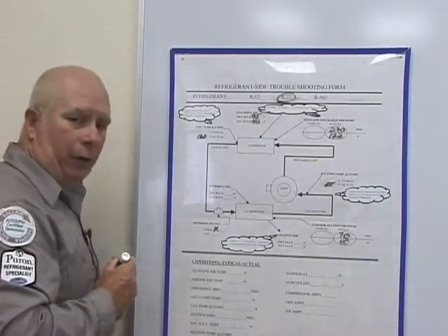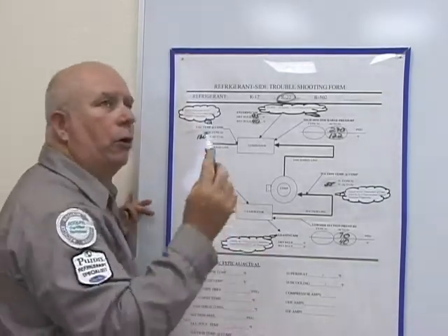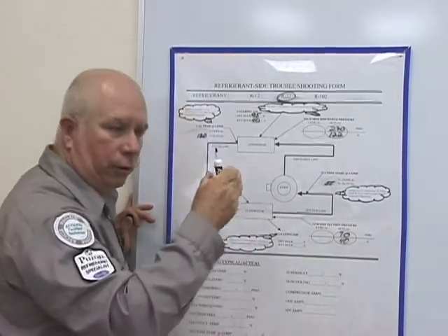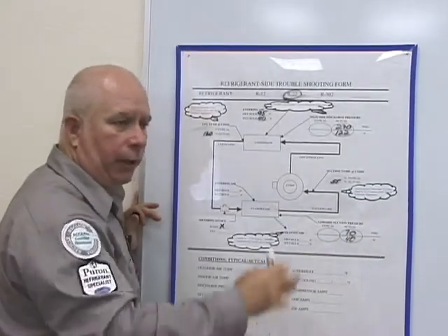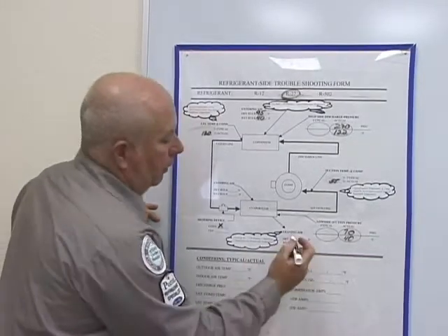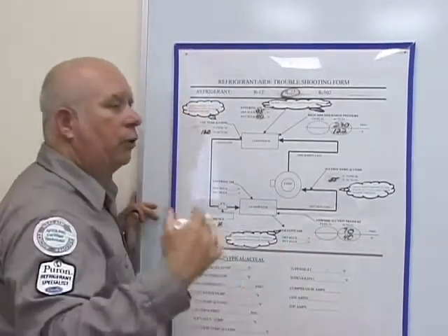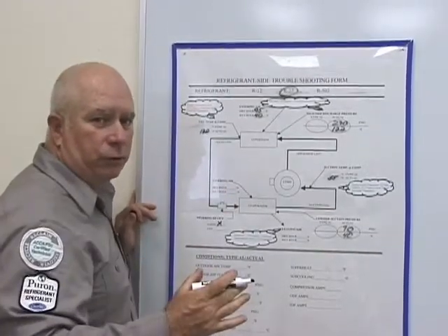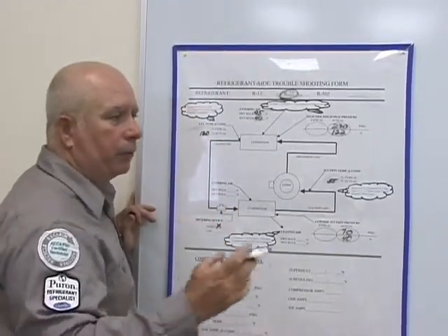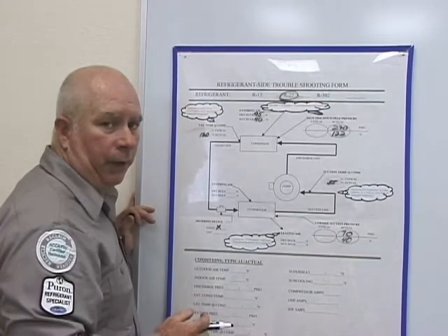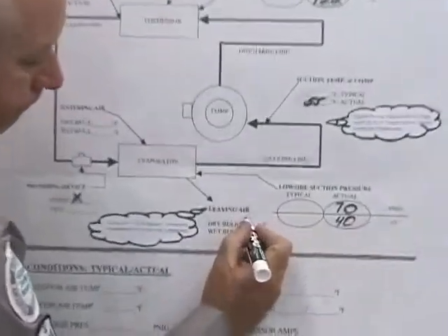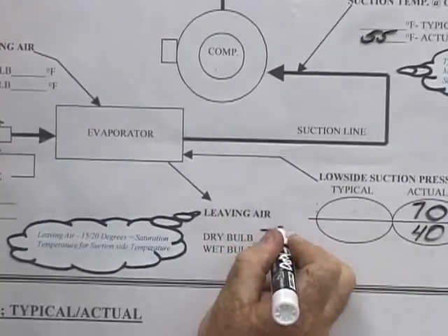Now, most of our measurements have been taken for the situation except for the evaporator. So we go in the house, and you're going to go preferably to the nearest register to your heat exchanger and air blower. You know, it could be in the hallway, but it's typically one of the bedrooms or the bathroom. Preferably get a larger vent so you get a true reading. But we'll say that it's blowing out 70 degrees.